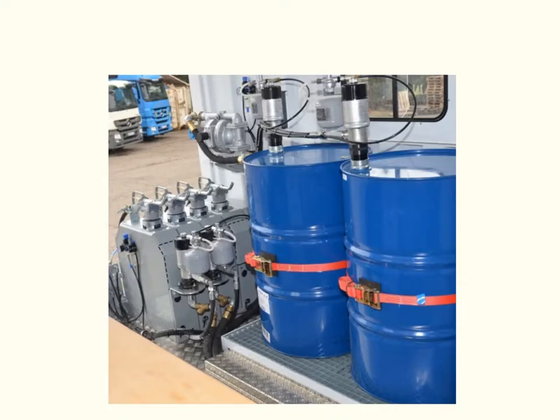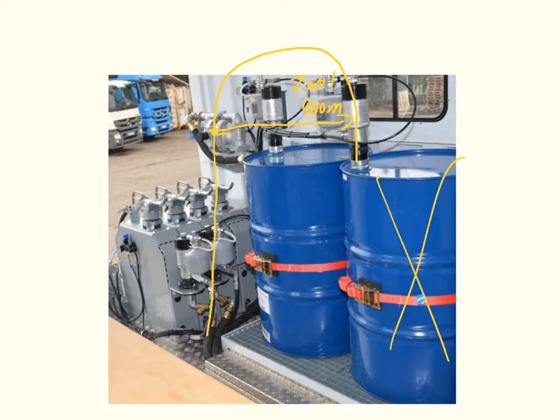All we have to do to address these locations is just draw in our Zone 1 and Zone 2 locations. So again, we have our dome, and we're just going to use one barrel here, so we're not going to address that barrel. But if we look at the fitting and the pump on this one, again, we're back to a radius of 900 millimeters out from center, and that's considered a Zone 1. Now, folks, that goes all the way to the floor, like this.